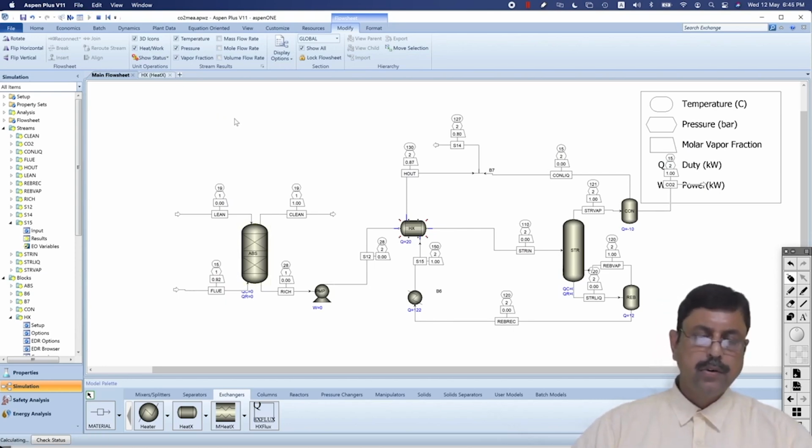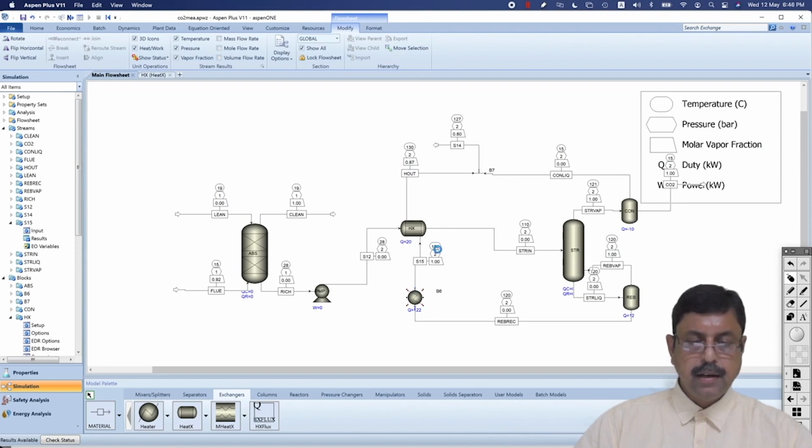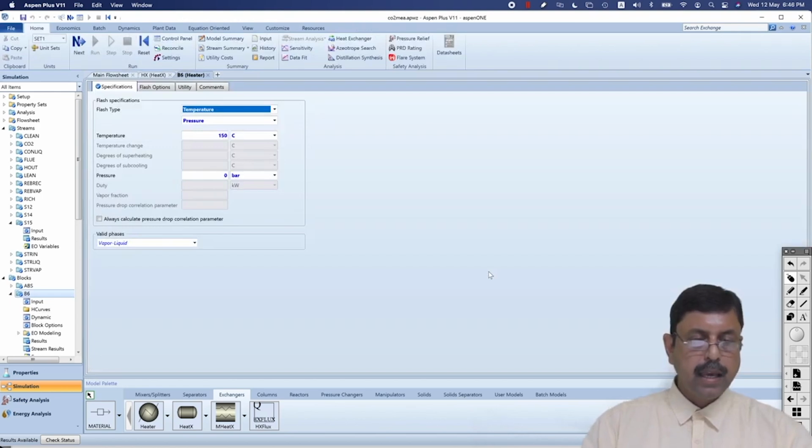Okay, so in the bargain we have got an even lesser amount of heat duty being carried over here. By decreasing the temperature, we have a fair estimate that perhaps now we have enough heat duty that we can transfer from this stream to this stream. Now let us decrease it from 150 to say 130 and check what happens.